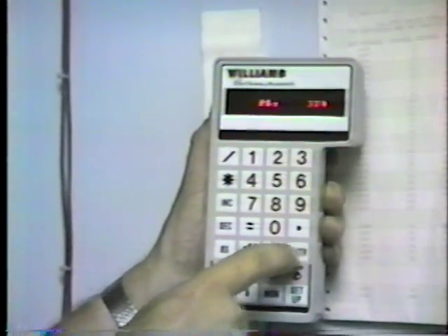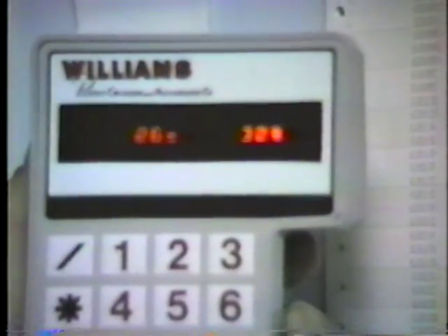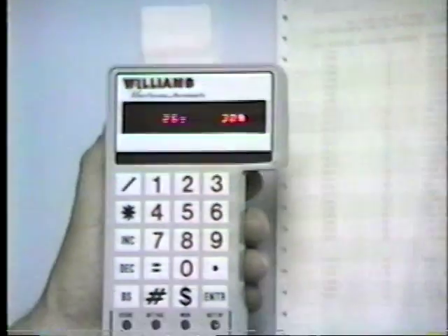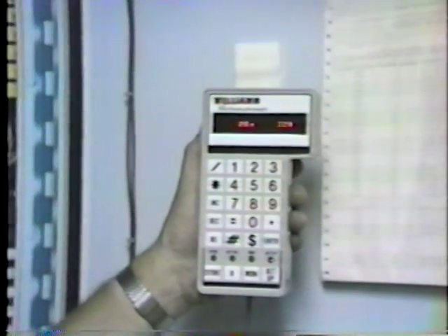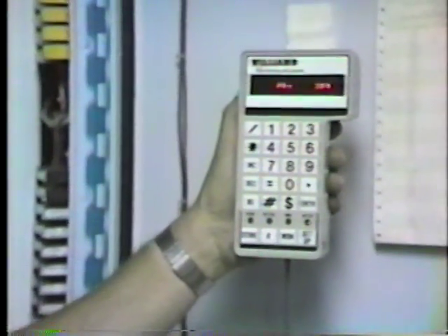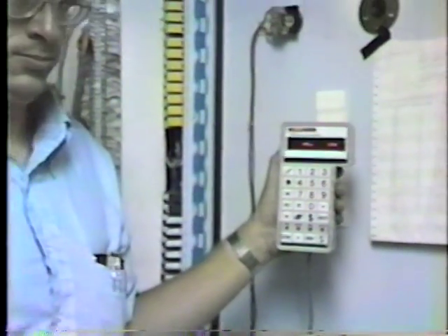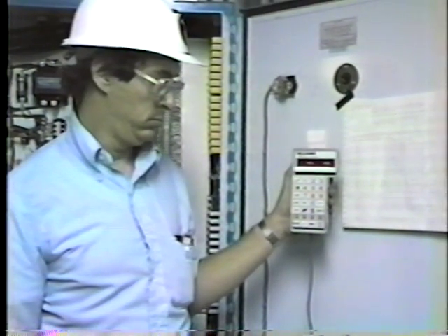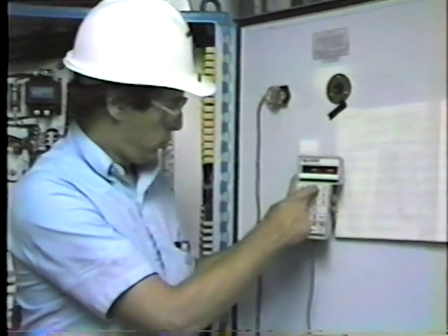26. 26 says 30 minutes. We've got 30 minutes and nothing's going to happen for 30 minutes unless somebody does something about the delta pressure being too low. Now, that would be an indication if the feeder runs out of material. And that happened today. The material was stuck in the feed chute, clay packed in there, and the low delta pressure shut them down after they ran out of material. Okay, go back to 24.